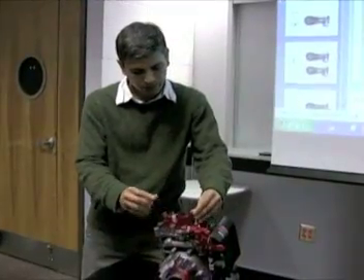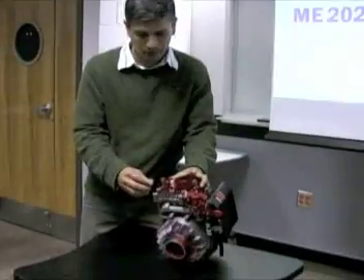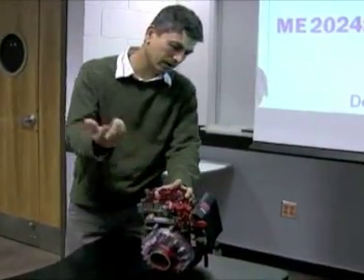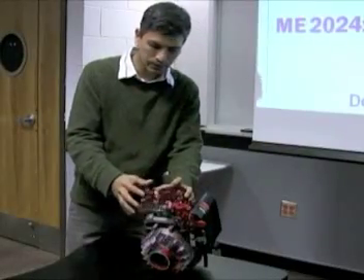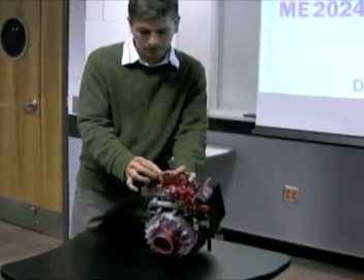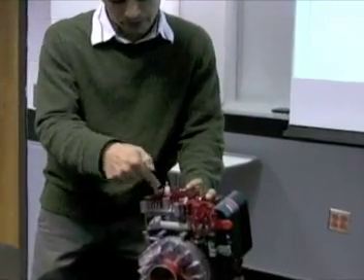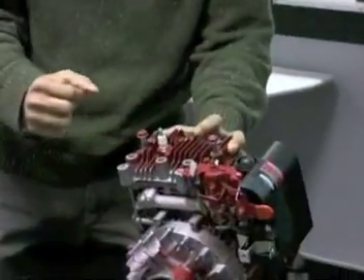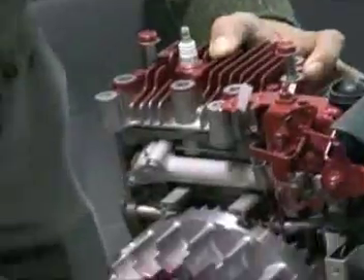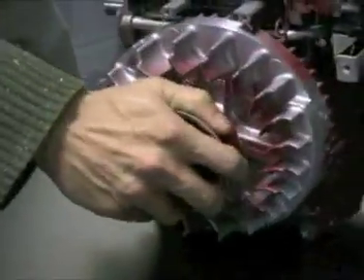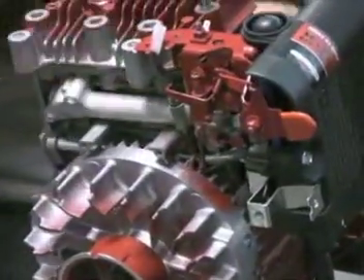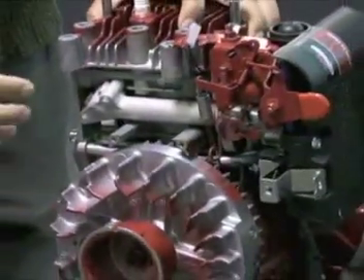Here is a one-cylinder, four-stroke engine, typically used in a lawnmower at our homes. What I am going to take off is the bulkhead at the top, which has the spark plug right here, which on the other side is the spark going into the cylinder. You've got two bolts here which come off. And then this is the crankshaft, which is connected to the drivetrain, and there's a shaft here which connects the motor to the wheels.